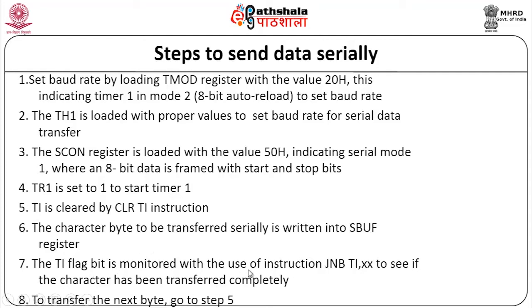Once it has been transferred completely, you have to clear this TI flag, send the next character to SBUF, then wait for TI to be set. Once it is set, you clear it, again send the data to SBUF, and wait for the TI flag. So this is the way serial communication is done with this loop.